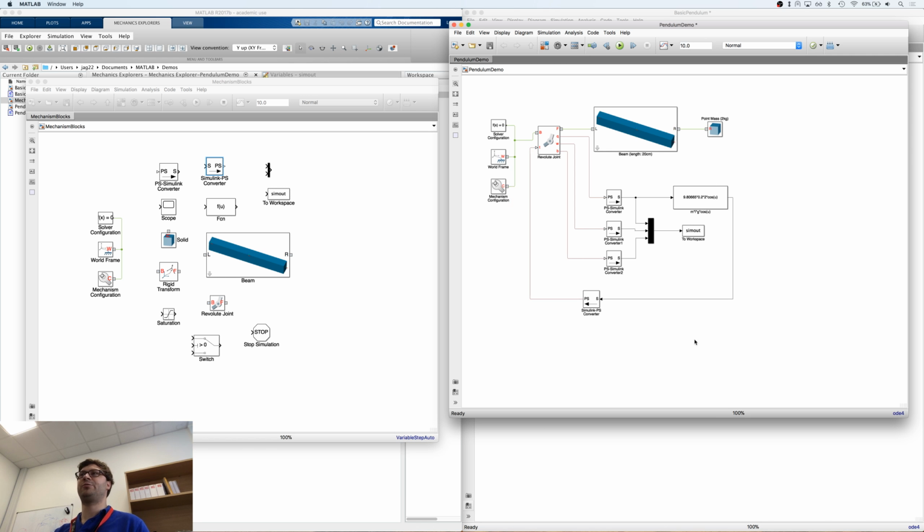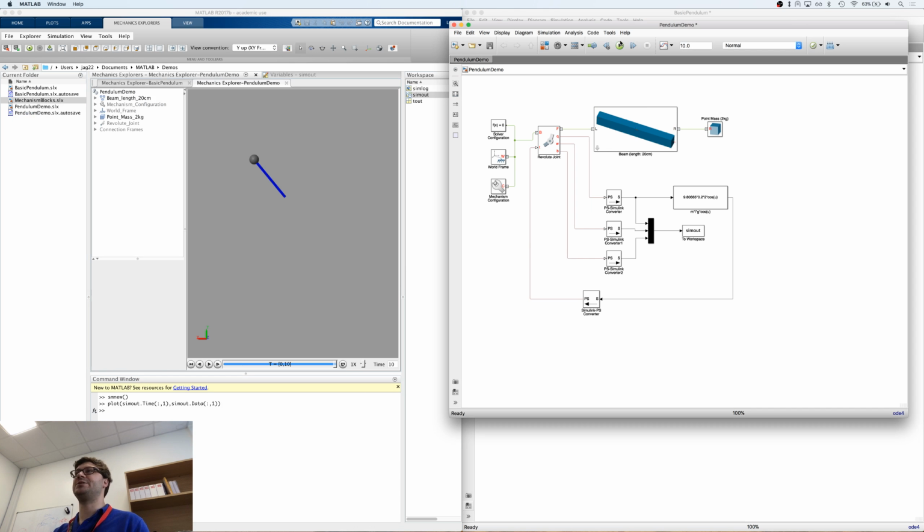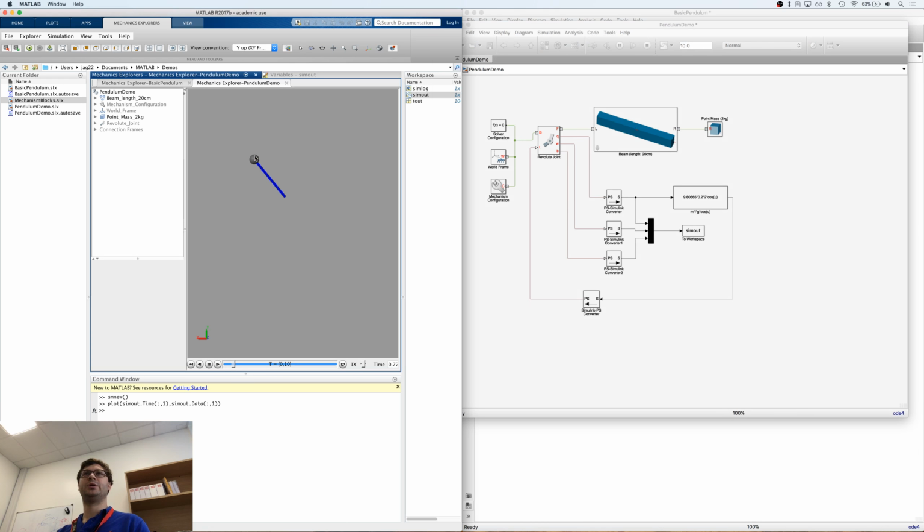As you can see, it's quite easy to understand. You're taking a displacement, performing a calculation on that displacement, and then feeding that back into the system to provide the new torque that's going to be working against the beam. Let's double check it's worked. If we click run and watch our system, as you can see, actually nothing's happening. That's the case because we're calculating the resistive torque needed to maintain the position of this pendulum.